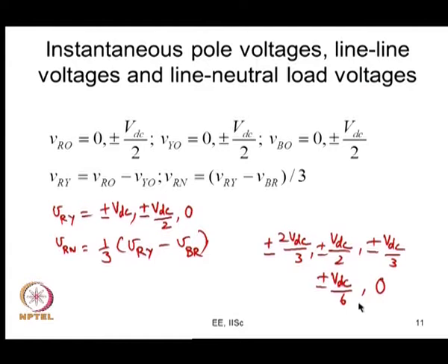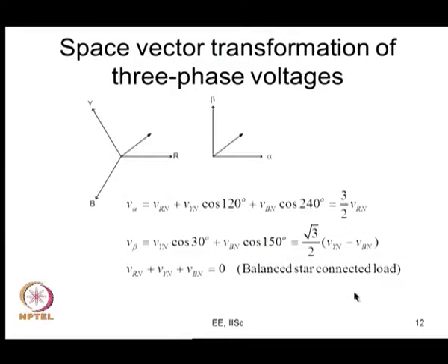We need a particular output voltage, that is what the load cares about, but that is possible to generate using multiple sets of inverter states, particularly when you are talking of voltages which are low in amplitude, so not close to VDC. So, this is what allows us to design many PWM methods now.